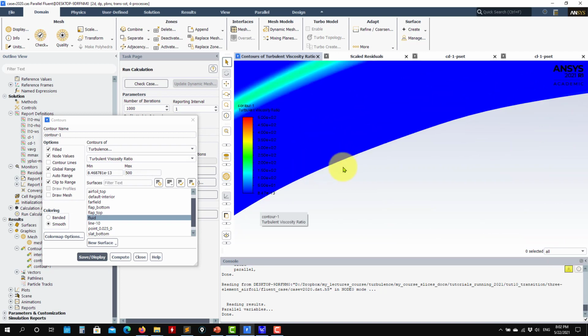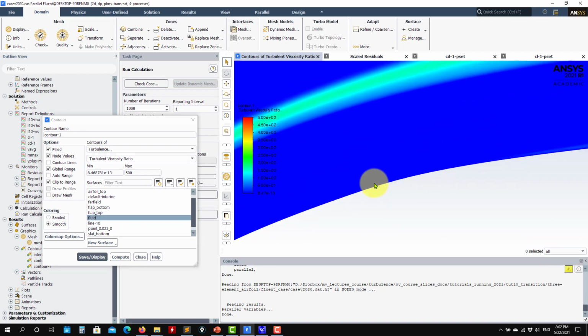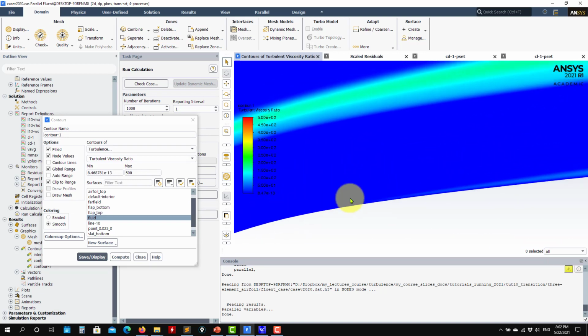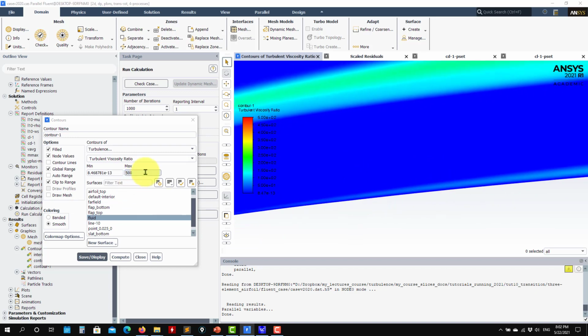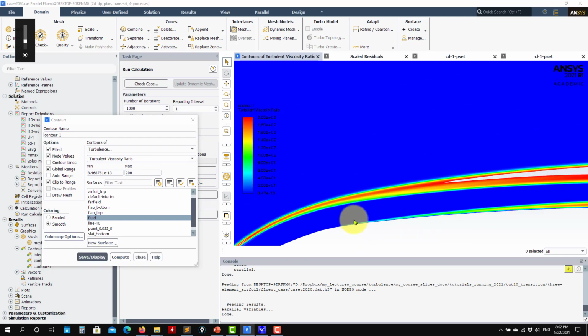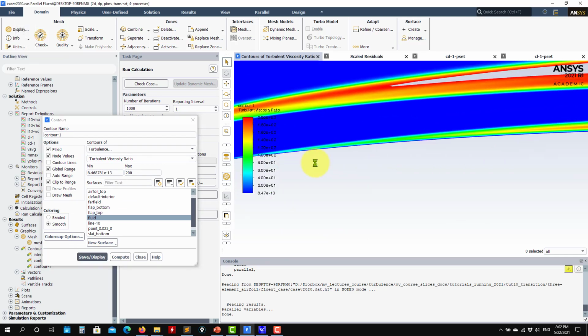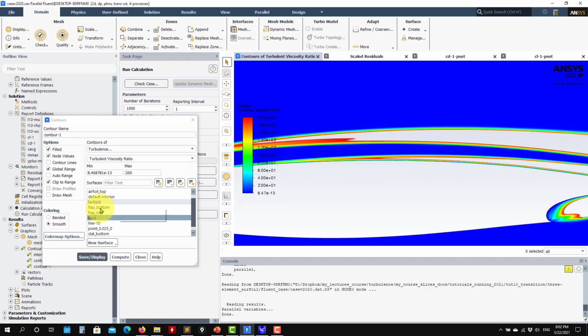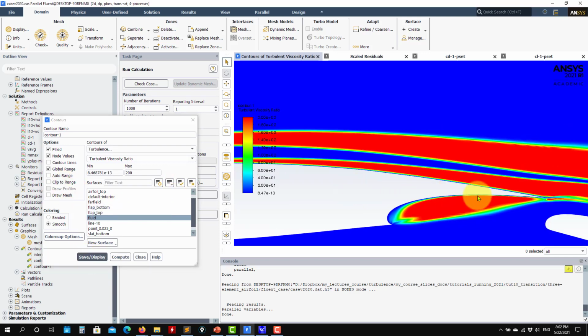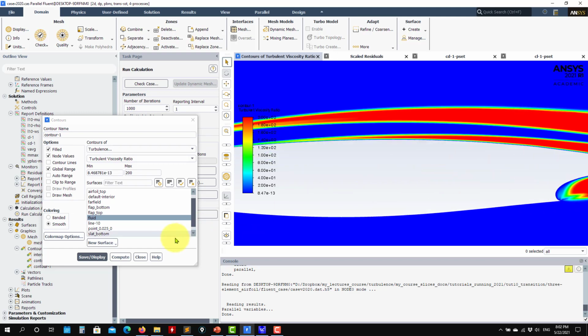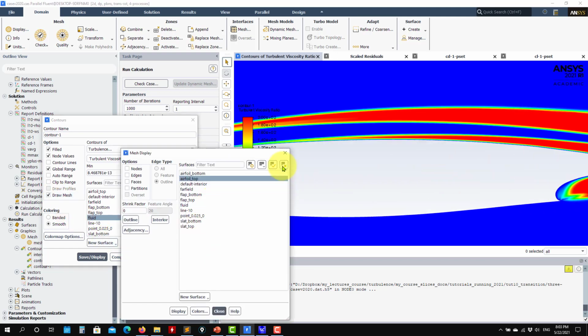See that everything that is 0 means that you don't have turbulent viscosity. See that boundary, and then here you start to see that turbulent viscosity. Probably if I reduce a little bit more, you can see better. See that kind of here will be your point of transition. And then as you plot your mesh over this one, you will see that you have a good mesh to resolve the boundary layer. Let's see if that is the case.